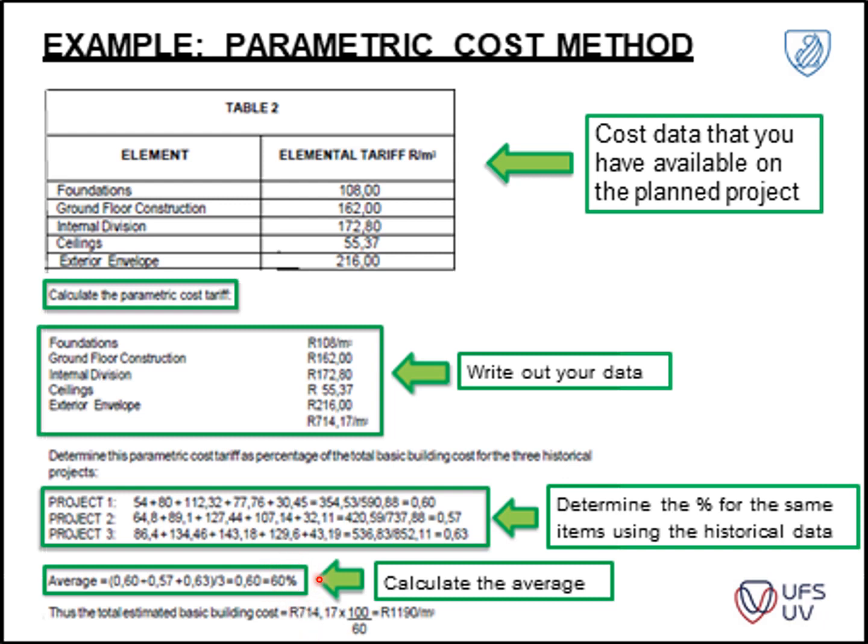Then you take this calculation that you've done here, the 714 Rand per square meter, and you extrapolate it with the 60%. So the extrapolation is basically you want to get to 100% here, and you currently have 60%. And if you do that, you can see, okay, the building rate should go up to 1,190 Rand per square meter.